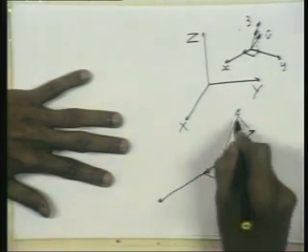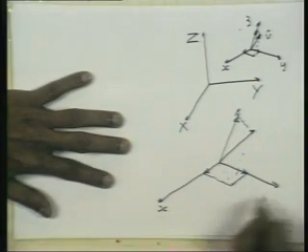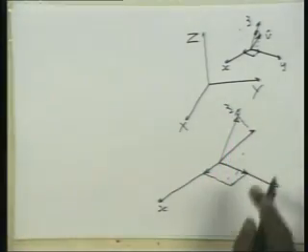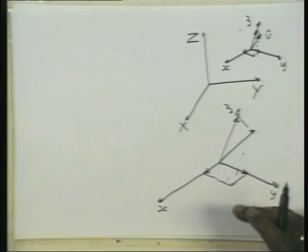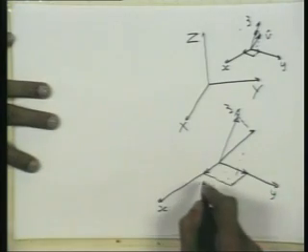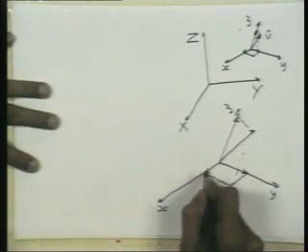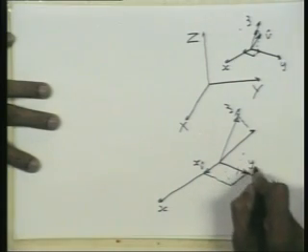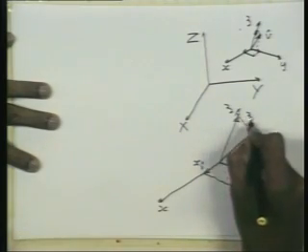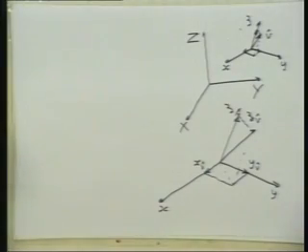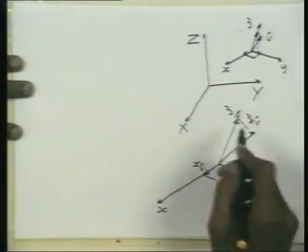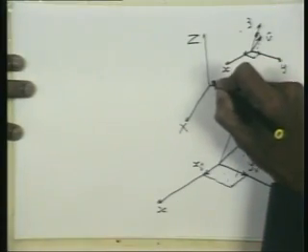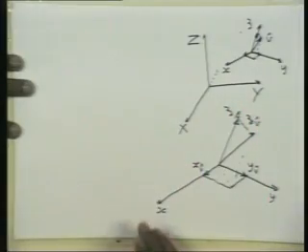look at the three projections along the three local coordinate directions. Those are the direction cosines of this vector, or this being a unit vector, they are nothing but the coordinates of the vector. Fine. So the length of this particular vector is small x v cap, right? That is how we give the notation. Small y v cap and small z v cap. So we know this. We need to find out the global coordinates of this. That is essentially obtained by transferring this vector here and projecting it along the global axis directions, and those coordinates are the global coordinates of that vector. Fine. Now we can do the following.